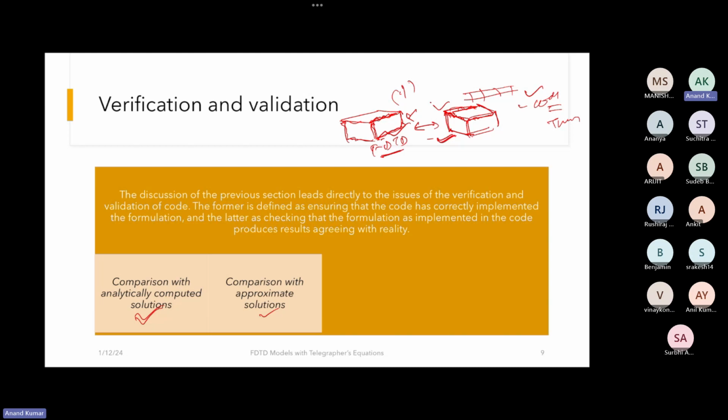So this is one way you can try to see. But if you're trying to simulate the rougher square and you end up with something which is very wrong, for example, infinite values, or your code is getting stuck, then you'll know that the code is not working okay. A better technique for solving the interaction of a wave with rough edges would be to verify your FDTD code for the square, and if that is stable, then increase the roughness.